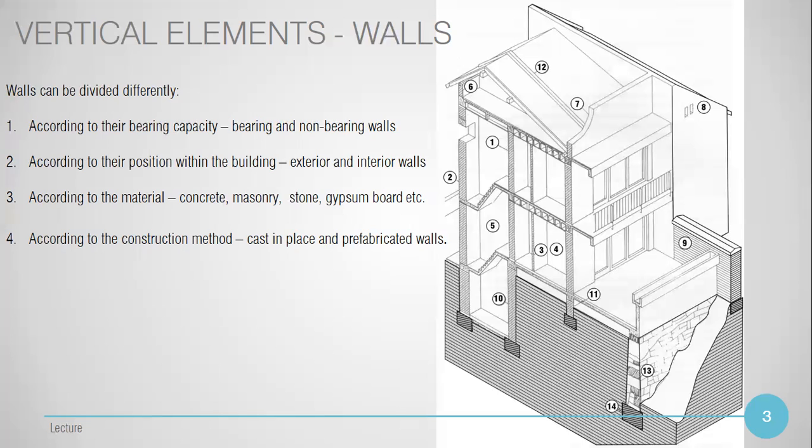If we apply a heavy material for walls, of course it will increase its own weight, and it will make the calculation analysis of the main structures more difficult. When we increase own weight, we need to apply stronger structures to be ready to carry all the weights.